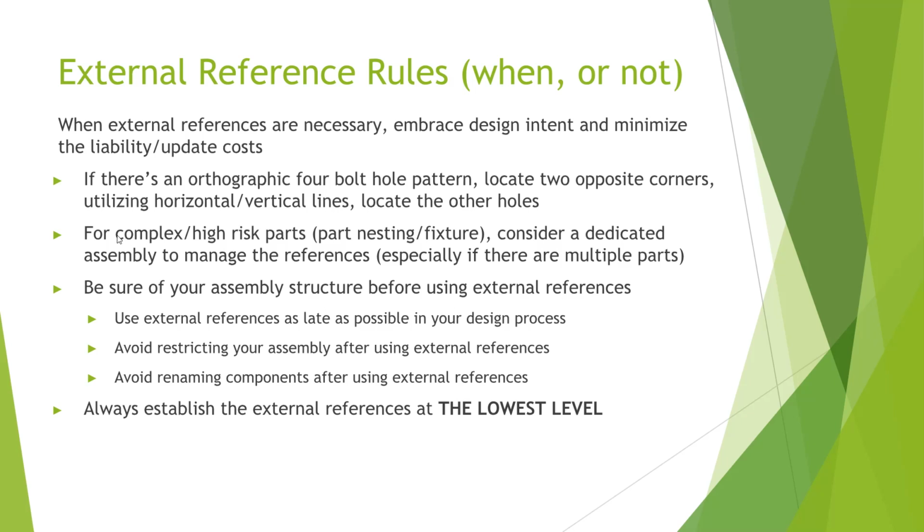So for very high complex or high risk items, and I have an example of this too, like if you're doing an offset surfacing of a part fixture, if you lost that external reference or it broke or a file changed or something like that, how much work do you lose if you spent, well, I didn't give you the answer, right? But if you spent however many hours doing a surface offset, knitting it all up, cleaning it all up, cutting it all out, and doing your nest, if that broke, that's a lot of time. So it is a viable option to have a dedicated assembly just to manage those references. And I have an example of that.